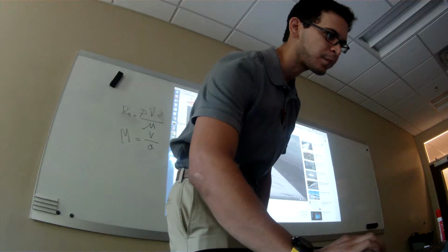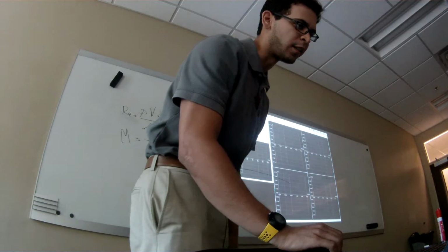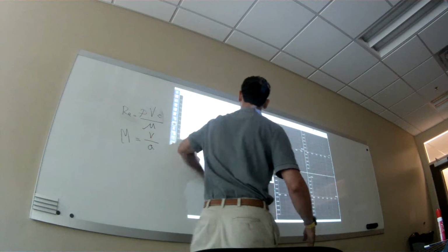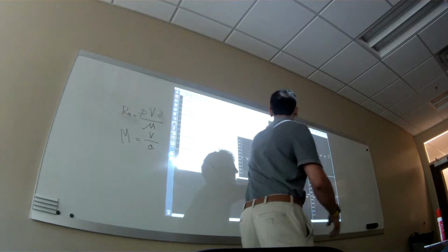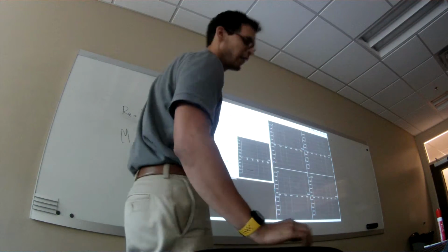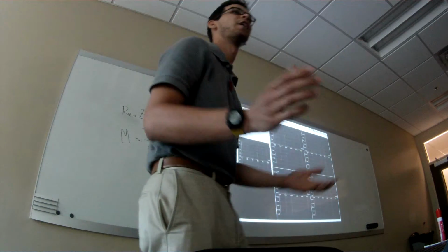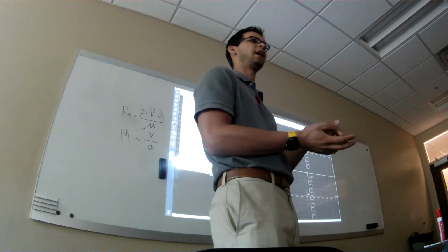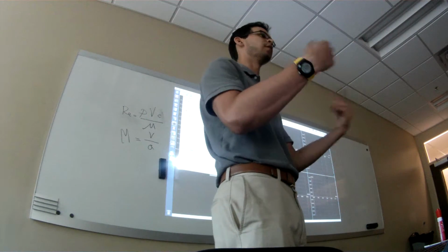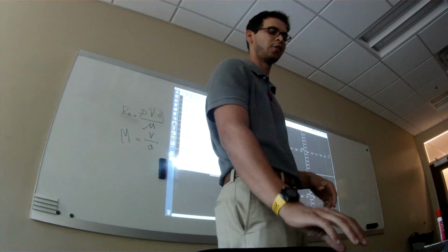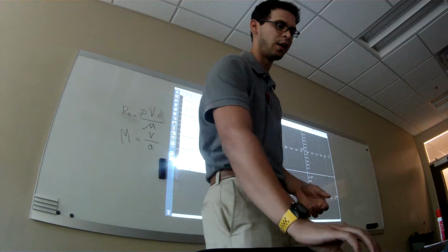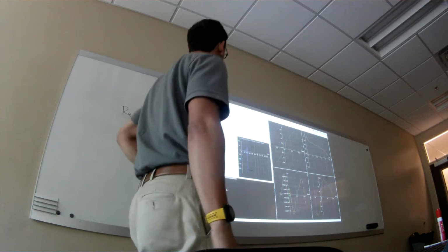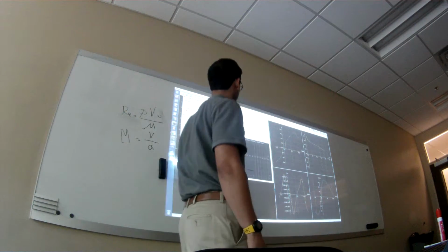All right, so let's go back to XFLR5. So I've got my angle of attack window, -6 to 12. I got my Reynolds number window. I got my foil list. So I'm going to hit Analyze. And the cool thing about this is that I think this was actually written in Fortran back in the day, but they compiled it. So it's actually going to use a numerical solver. Yeah, so it actually matters, learning all this stuff, but it does it for you. I'm going to hit Analyze, and it's going to converge all of these things. And you can even see how many iterations it takes to converge.